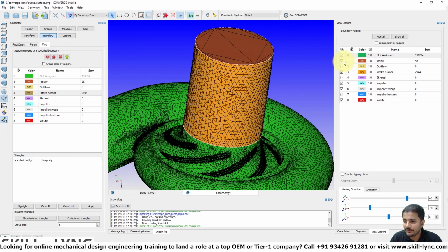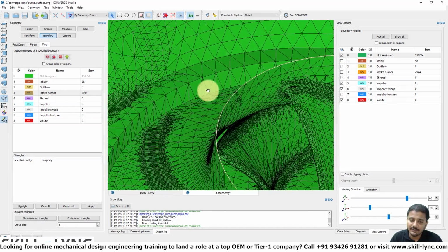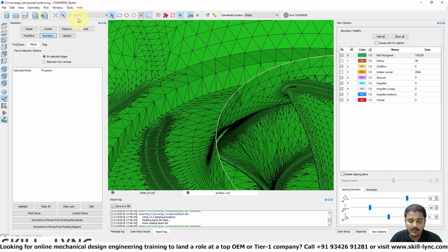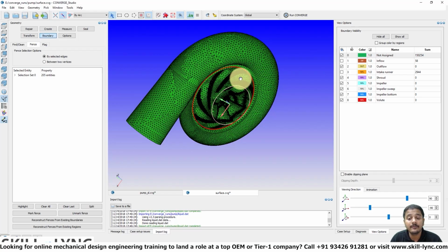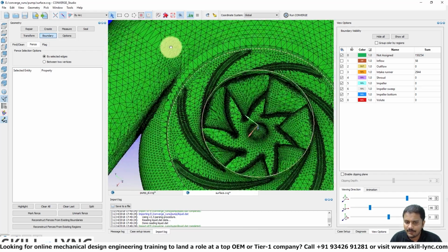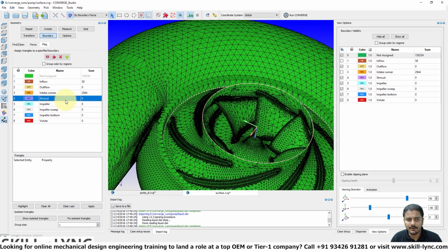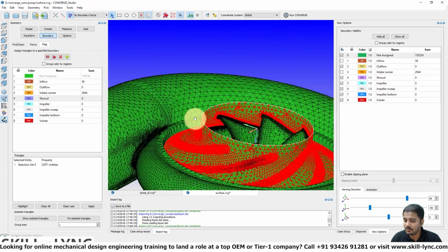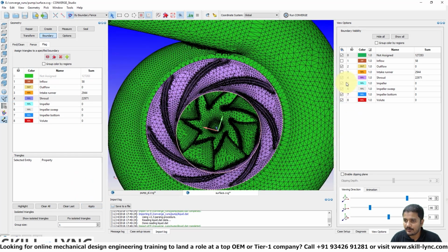So what I'm going to do next is hide the inflow and the intake runner so that we get improved visibility. Alright. So you can see that the shroud kind of ends here. So I should be able to go back to fence, use the arc method and select this particular guy. That looks pretty good to me. So let's hit enter to create the boundary fence. And always verify. Whenever you create a boundary fence, you need to look at the geometry completely to see that the edges have not been flagged incorrectly. So then let's go to flag, and then we're going to click on the shroud, use the boundary fence method. Boom, there you go. That selection looks good. And let's click apply. Okay, so now I think we can hide this guy.